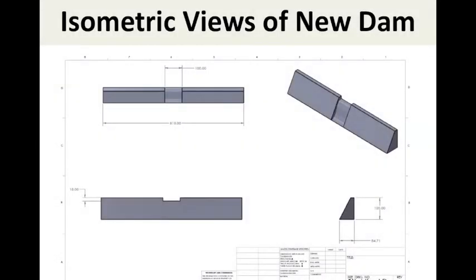This is the final design of the replacement dam at Lake Wohlford, modeled in SolidWorks. As you can see, the spillway is 100 feet wide, thus giving us an appropriate flow rate in maximum rain conditions. Also, you can see that the height of our dam is 120 feet tall from the subsurface soil level. This allows us to achieve a 30% additional volume to Lake Wohlford. The top elevation of the dam is at 1,510 feet.